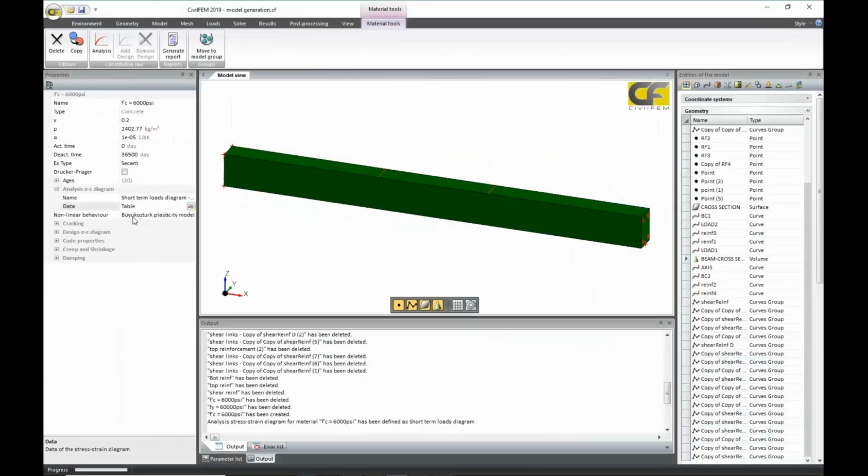Also, it could be done with the Drucker-Prager plasticity model or isotropic plasticity model. I'm going to use isotropic plasticity models with loaded and unloaded curves, following the elasticity modulus and plasticity deformation, which will be easy to plot, those plasticity deformations. Well, that is for concrete nonlinear behavior for compression.